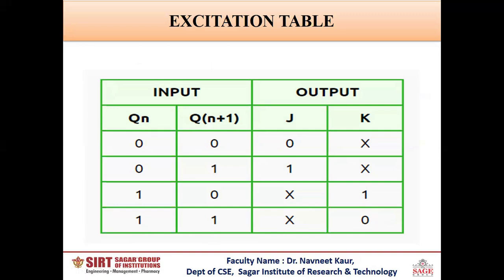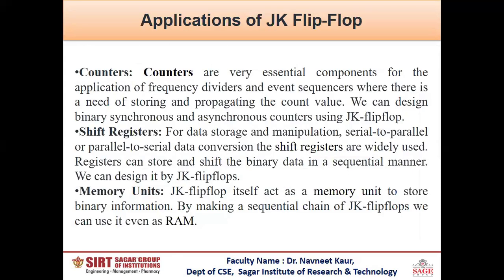So this is the excitation table, which is also used for the designing of counters. Now, coming to the applications of the JK flip-flop: JK flip-flops are used in the designing of counters. Counters are used for counting sequences. So we can design binary synchronous and asynchronous counters using JK flip-flops.